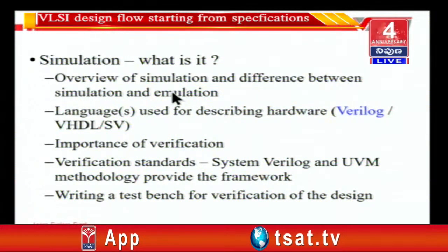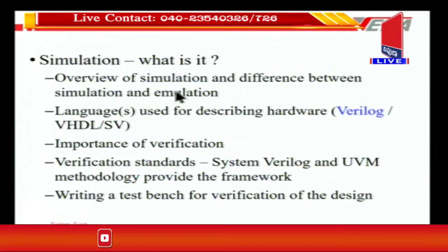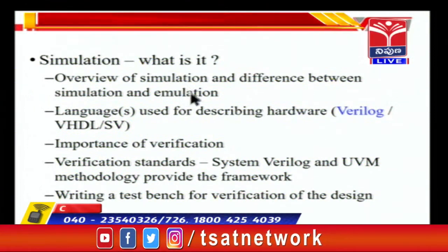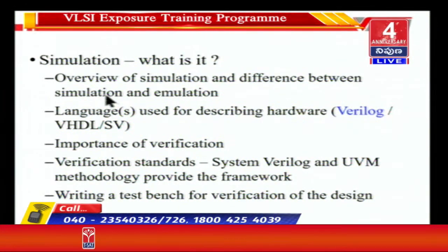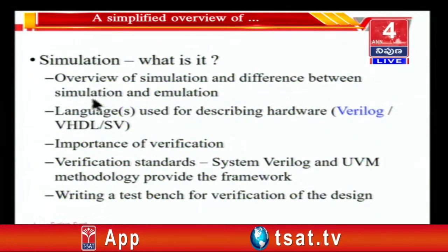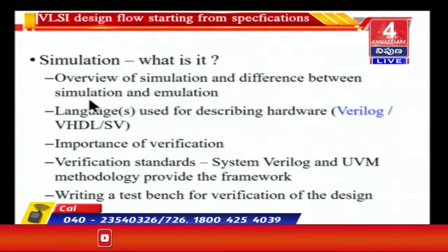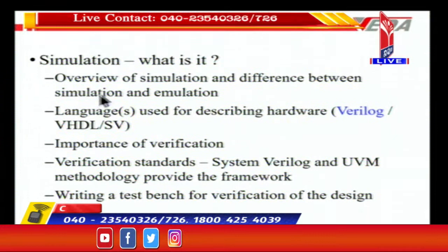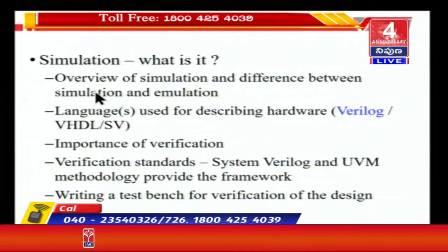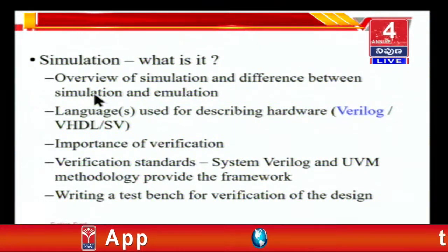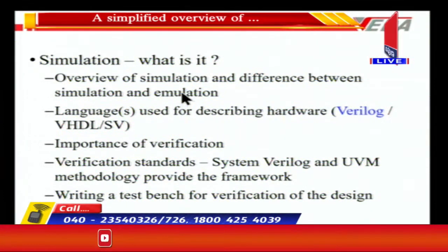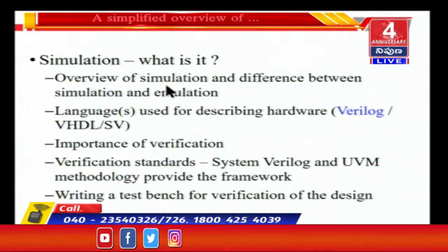Simulation is much slower compared to emulation. Now, a 10-second program will run in 10 seconds on an emulation platform, but a 10-second program of a microcontroller might take maybe several minutes or several hours to run when it is run in simulation. That is the difference. So, emulation is almost always real time, whereas simulation is not real time because it gets executed in software on a single processor. This gets executed on a different platform and this runs in real time. That's the difference between simulation and emulation.